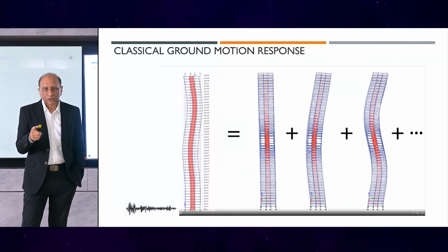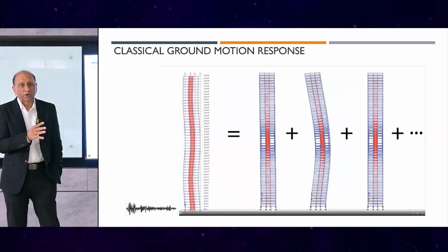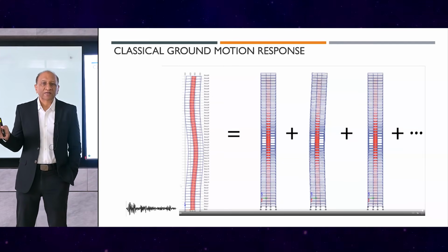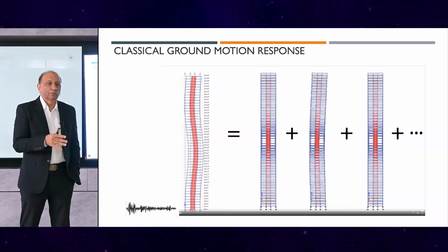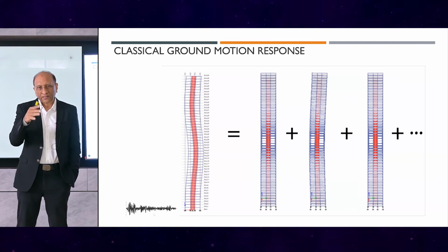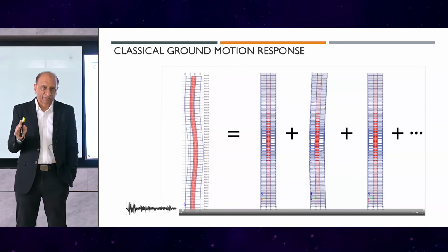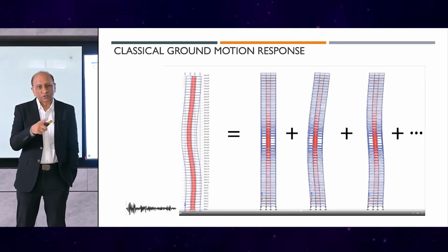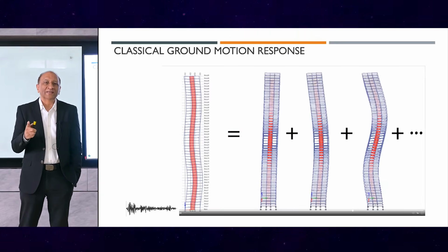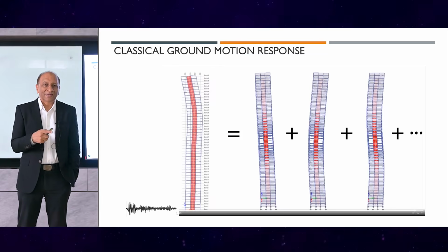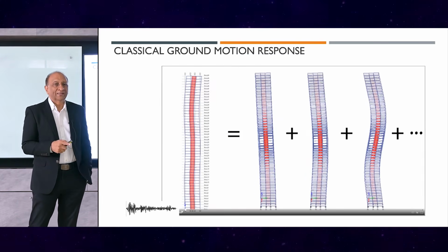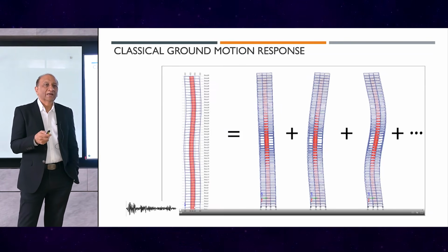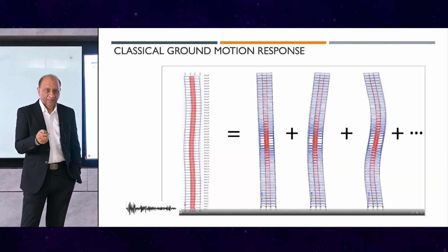And then if we have a ground motion, then to get the total response of the structure for the ground motion, the responses of many of the modes will be added together, combined with the ground motion, depending on the way the structure is moving. It's a complex thing, but physically, the sum of the modes will give us the actual vibration of the structure, because those modes are independent. But when they're added together, depending upon the ground motion, you will get a certain movement. And that's how you can derive it. We will talk about the ground motion, and all of that stuff.